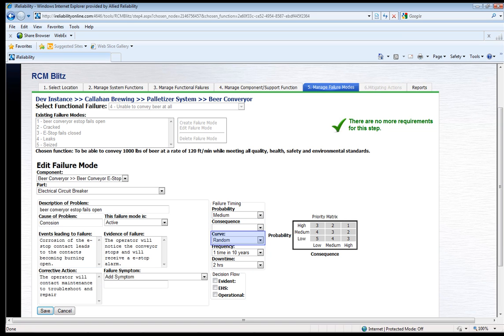Curve. The following definitions apply. A equals bathtub curve, typically electromechanical devices such as limit switches, push buttons, relays. B. Classic wear, wear-based components that have been installed using precision maintenance including belts, sheaves, pulleys, chains, and sprockets. C. Steady wear, wear-based components that once installed and put into service, the conditional probability of failure increases over time. Pipes, tires, clutches, and brakes are good examples.